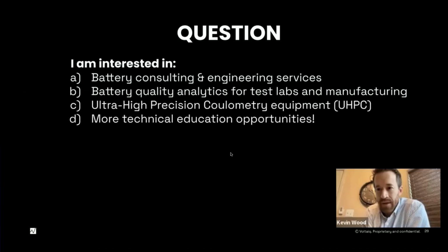Yeah. There was a question in the chat that I think is really interesting, and I'll honestly have to think about this a little bit more. Somebody was basically asking, are there any special considerations or complications related to doing DQDV when cycling at constant power, charge and discharge? And the answer to that is going to be yes. There's definitely going to be complications, because you're not really at a constant current then anymore, because you're at constant power, right?